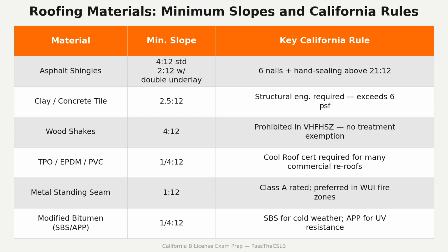Materials. I want to give you a framework before the details. I organize roofing materials into 3 functional layers: steep slope surface materials, low slope membrane systems, and underlayment. Hold that structure. Steep slope surface materials first. Asphalt shingles dominate residential construction. 3-tab shingles are flat profile, economical, and lower wind rated.